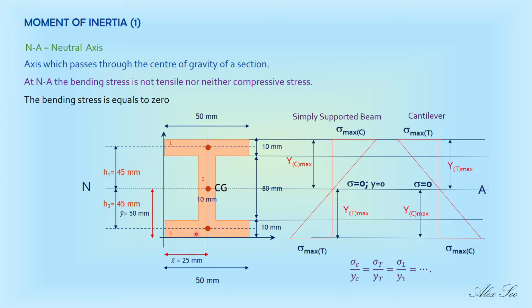Then you use the second moment of area method to find the moment of area of section 1 about the neutral axis, because we are taking the moment about the neutral axis. That means we assume that the beam will bend across its neutral axis.